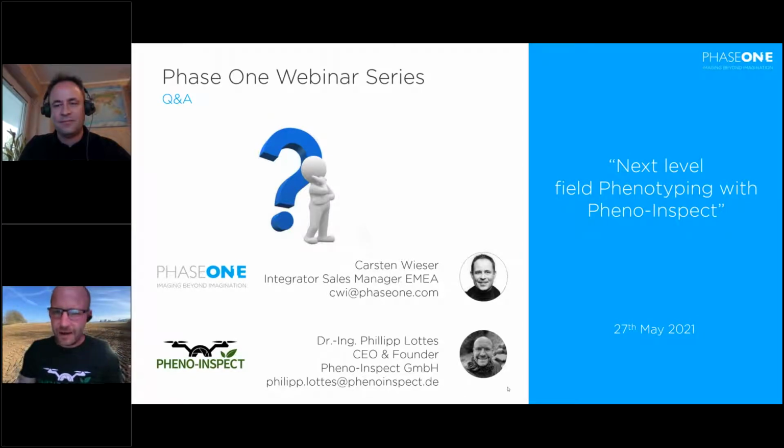If you have a big field, let's say 4 hectares of research trials, and you want to count every single ear on the field, then it's recommended to use image sensors which provide you with a high resolution and a high quality. But you can also use the Phantom 4, to be fair. You have to fly lower. You have to make sure that your ground resolution is around 2 millimeters or below, in order to get 90 plus percent accuracy.